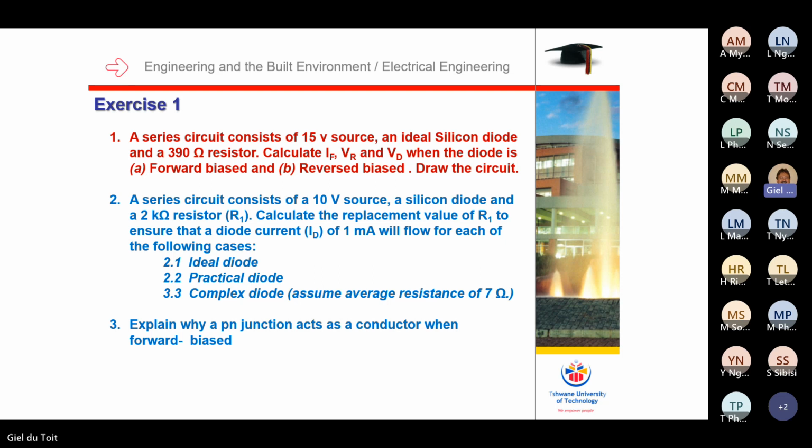I'm gonna put my 2K there again. I'm starting with a 2K and I can see it's wrong again because now the voltage here for the second diode, which is a practical diode. A practical diode means a normal diode that you can buy in a shop, a normal real life diode, okay, a physical diode. For a practical diode, this is always 0.7 volts. So to get the current here is 10 volt minus 0.7 gives me 9.3 volts.